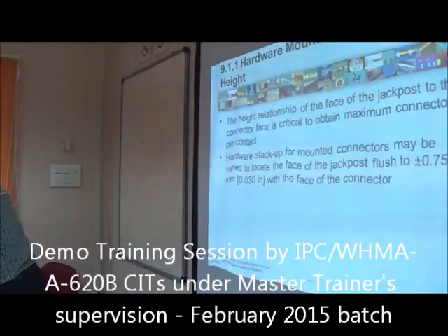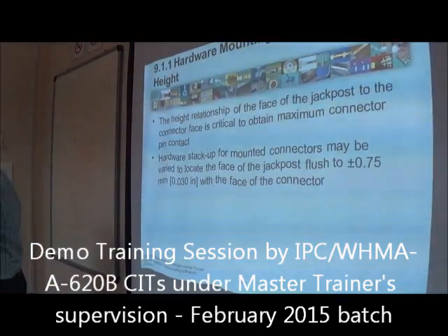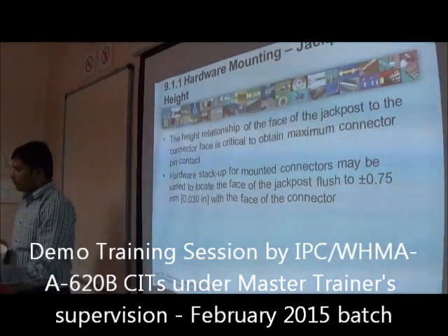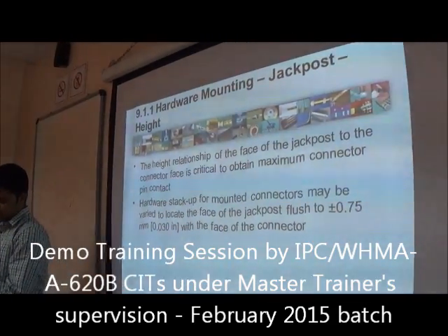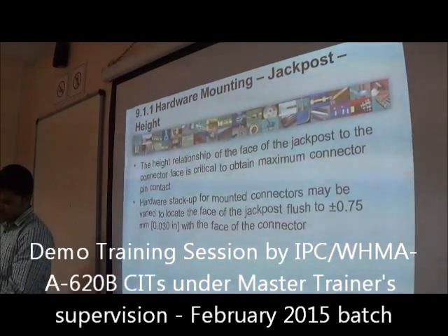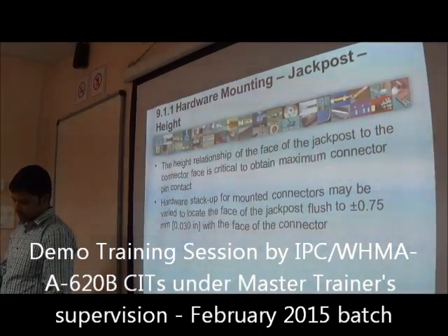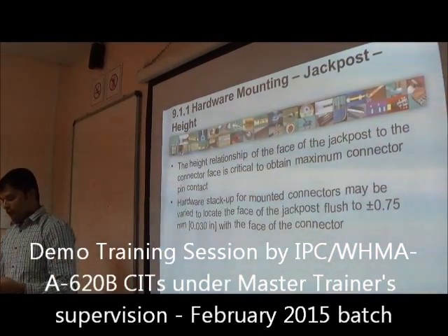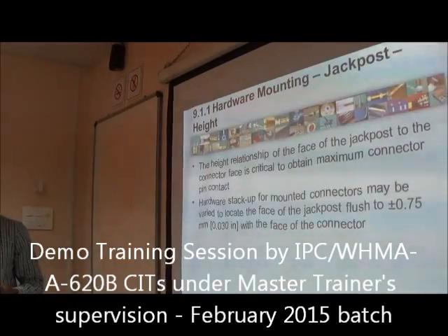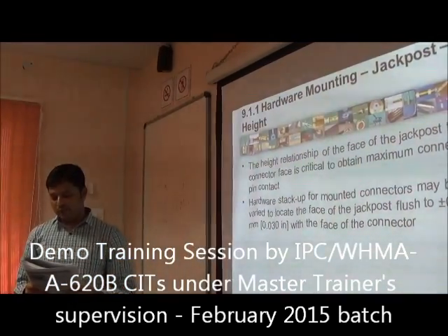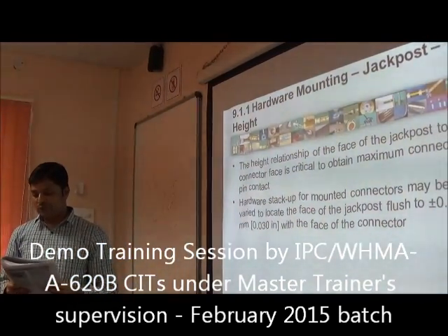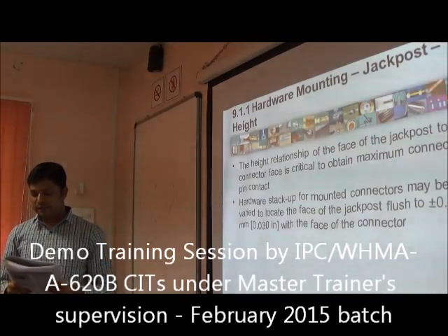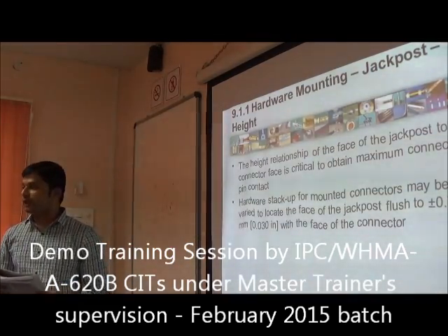Fine. So section 9.1.1 deals with hardware mounting jack post height. This section covers the height relationship of the face of the jack post to the associated connector face. This is critical to obtain maximum connector pin contact.